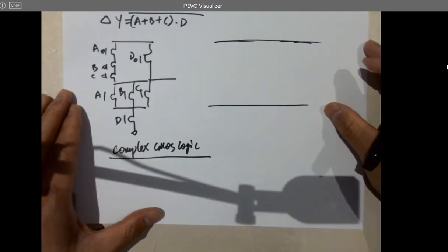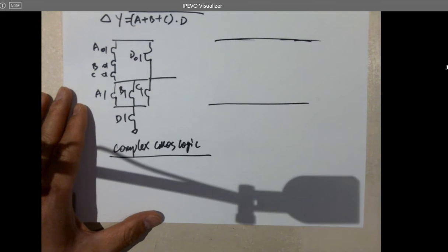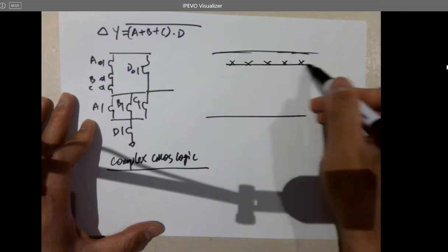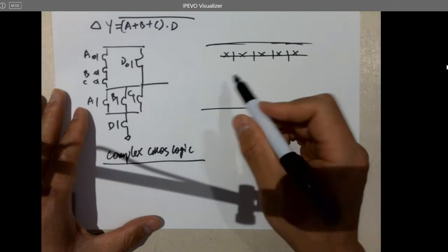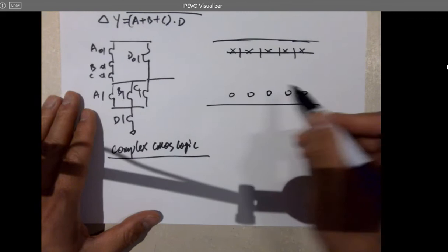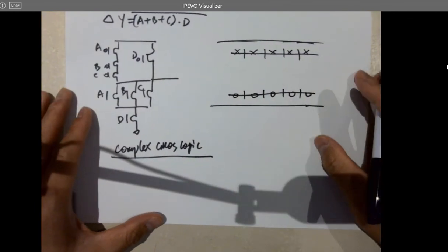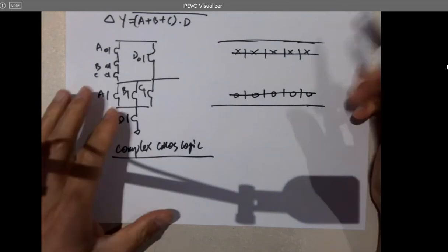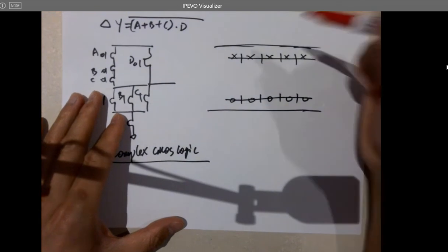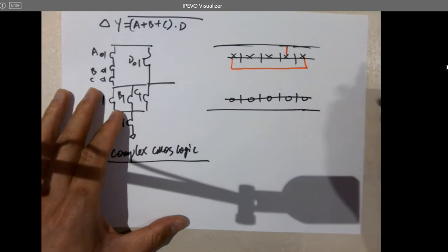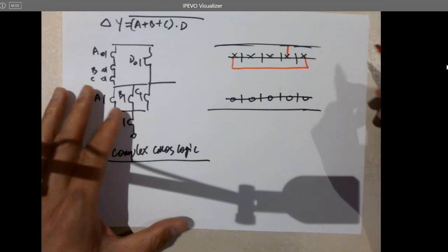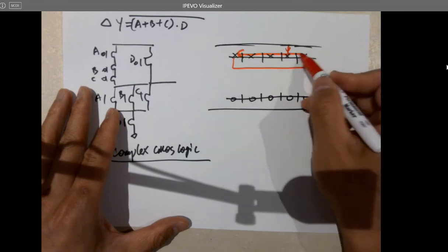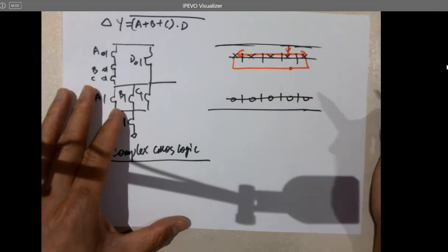Layouts to rails. One, two, three, four. So we need 5 diffusion nodes and 4 gates. Three are in parallel. Three are in series. One is in parallel. How to make it happen? What about that? Yeah, either way. Good. So one line introduced and 2 branches, boom, in series, another single one, and merge to one joint here. So they're in parallel.